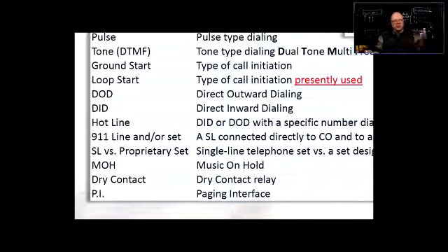Or they're going to tell you, we want a 911 phone here, and because it's a big company, big building, another 911 phone would be somewhere there. So you need to run a POTS line to one of the 911 telephone set locations, and you need to run a separate POTS line into another telephone set that is somewhere else.